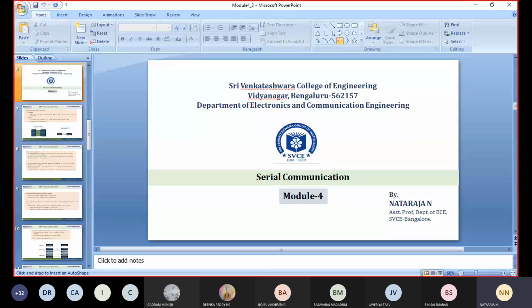That is the major introduction to communication. With respect to that, here we preferably use serial communication. We are going to transmit serial data. Why? Because here we deal with digital numbers, ones and zeros, and at a time we cannot transmit those things. There would be some complications we would face. That is why we use serial data communication. Serially, we transmit the data.